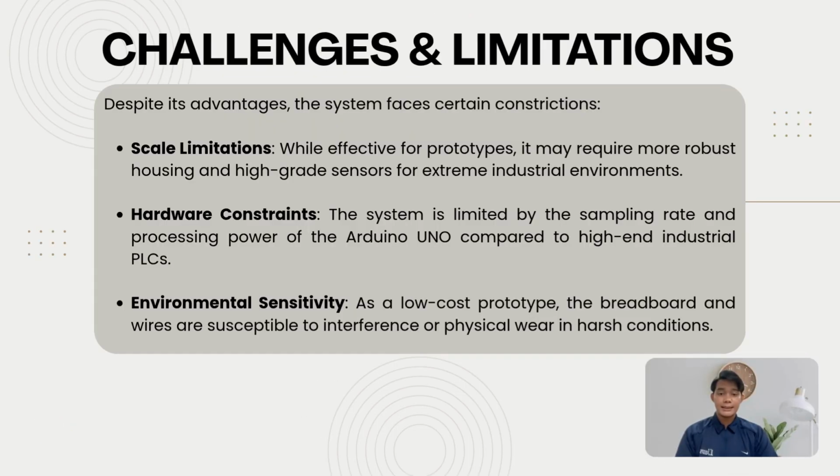Now, to be realistic, this is still a prototype, so it has some limitations. Because it is built on an Arduino Uno, it just doesn't have the processing speed of a high-end industrial PLC. Also, because we are using a standard breadboard and jumper wires, it is pretty sensitive to the environment. Harsh conditions or interference could easily disrupt it. To scale this up for the real world, we definitely need tougher housing and industrial-grade sensors.